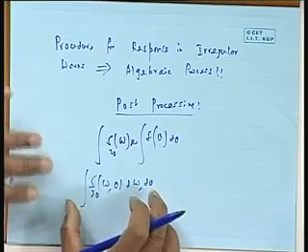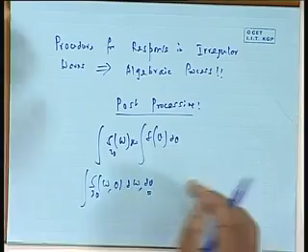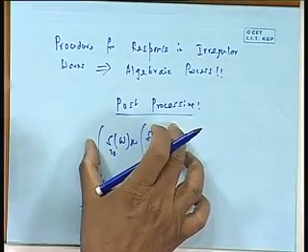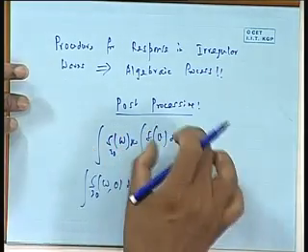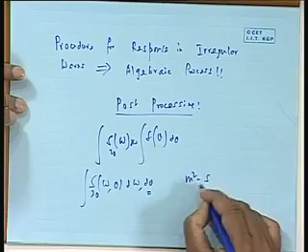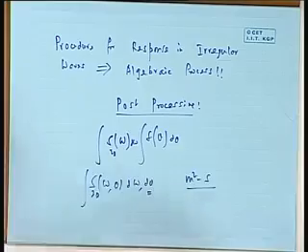Now what happened? You see that the units are the same because integration over d theta does not contribute to unit. D theta is radian, which has no unit, therefore the unit is still meter square second. This unit also remains meter square second because this is meter square second, this is no unit. So the unit is still meter square second for the wave part, and for the response part it will be the unit of the response square into second. So there is no contradiction whatsoever when you do it over the angle, because angle does not have any unit. Okay, so that also should be remembered very clearly. Okay, this is very briefly.